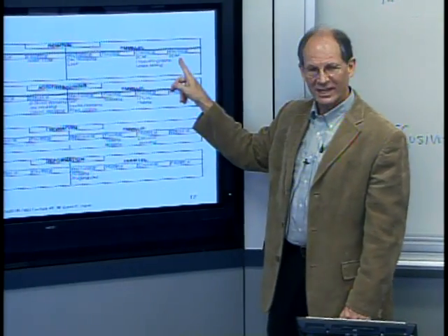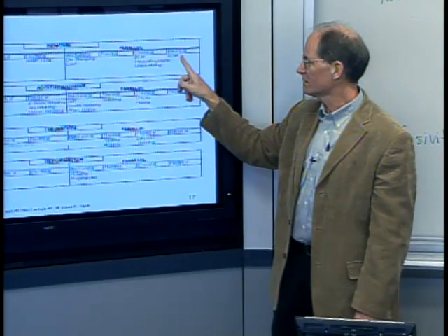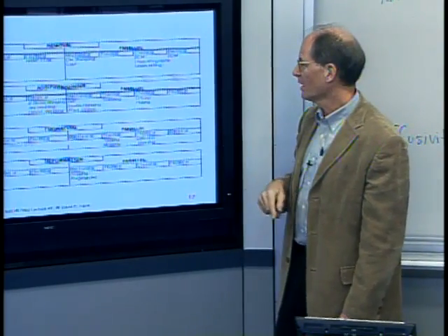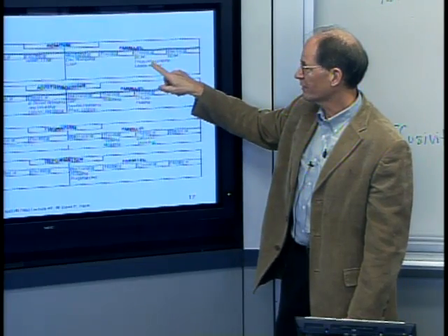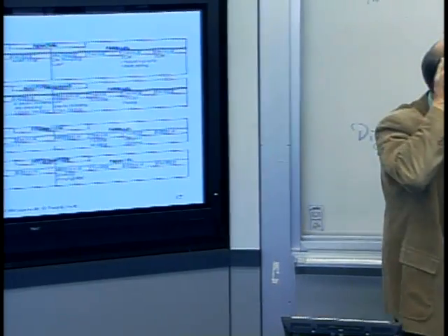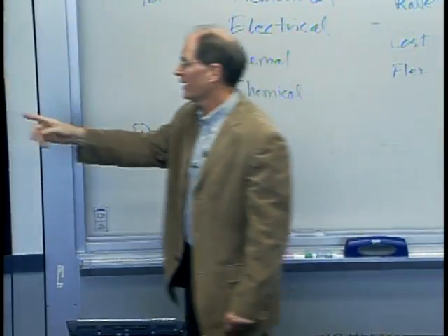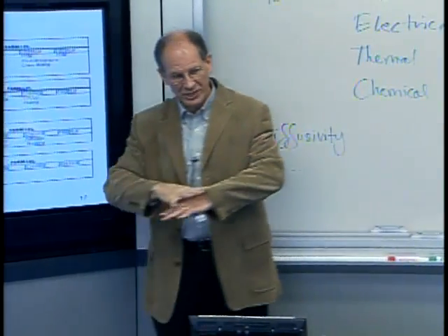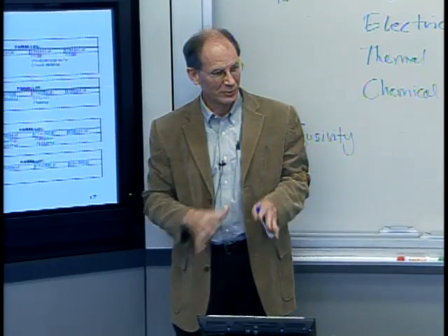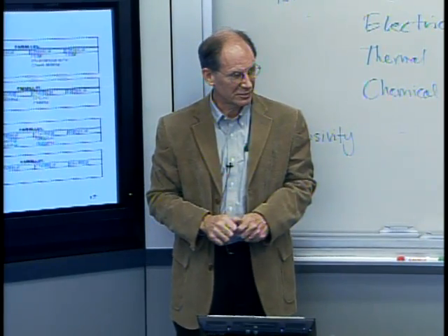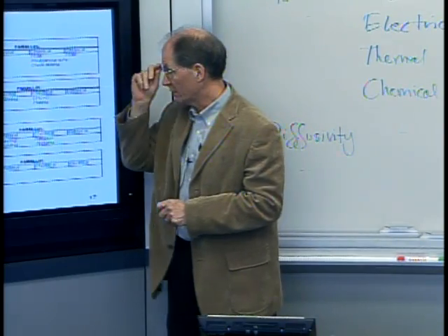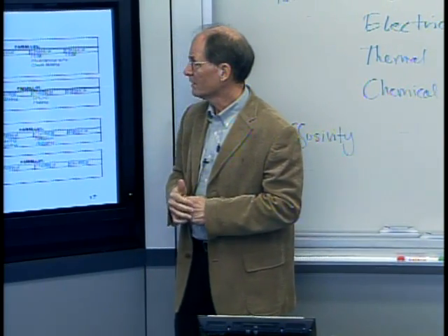Put a whole bunch of them together, do it all at once, say with a formed electrode. Now it's parallel EDM. Photolithography with a wet etch, if you want to think of it that way, is basically a parallel process. It's etching everywhere at once, but you just happen to put a mask in a few places. That's your tool, so that it can't, resist.